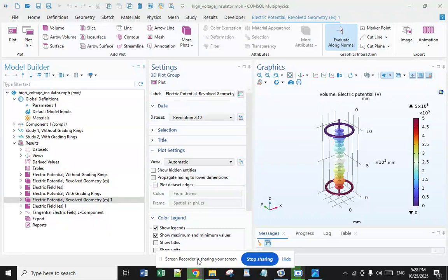This makes them ideal for use in electrical substations where they must withstand not only the weight of electrical equipment but also the dynamic forces that can be generated during normal operations or fault conditions. In addition, support insulators are critical in the configuration of substation equipment such as circuit breakers, transformers, and disconnectors, ensuring that these components remain electrically isolated from earth and from each other.